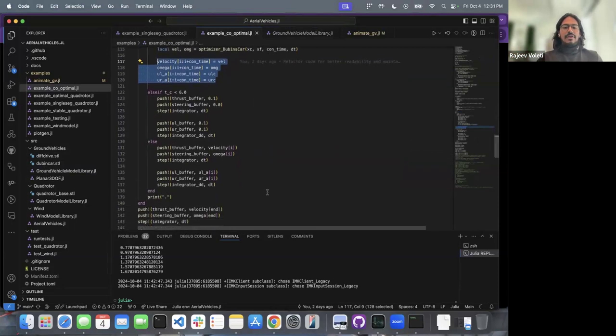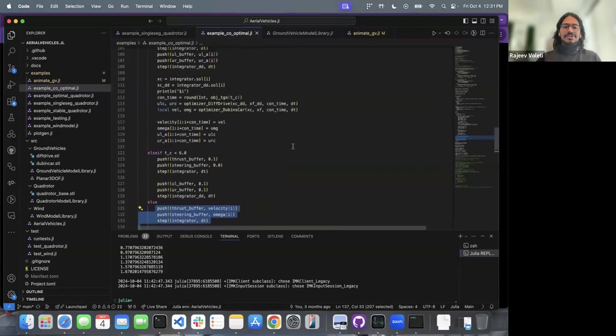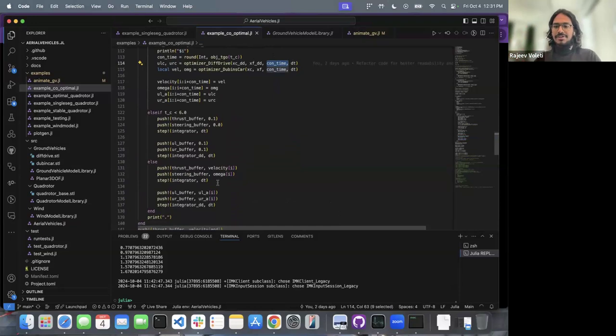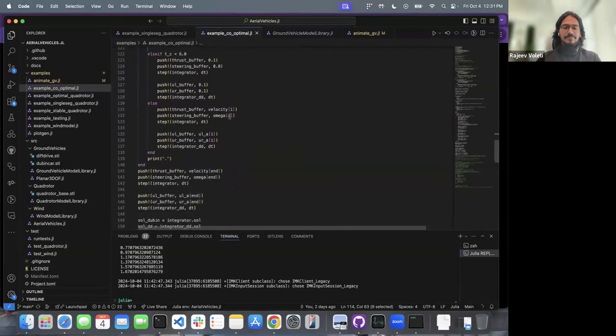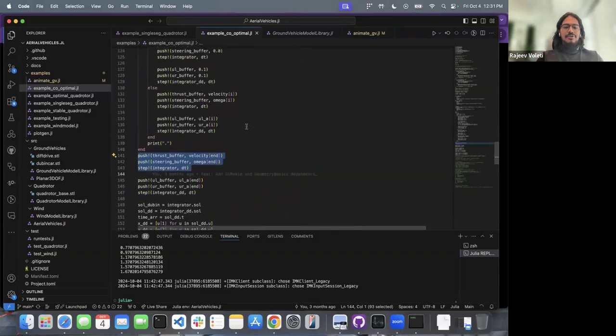Now, what happens in between time to go consensus intervals? Because this is a generated array for up to the time to go of landing, you can just locally push the generated trajectory that you have obtained, and this will reset every 1 second. And so at the end, since the control generated will be 1 less than the state vector, I push it 1 final time.